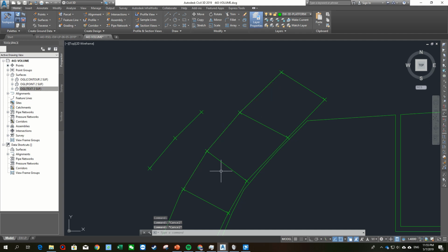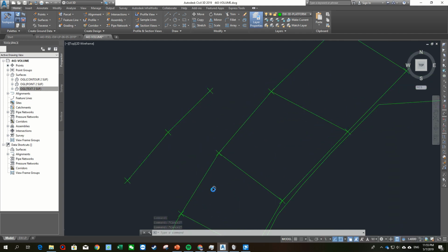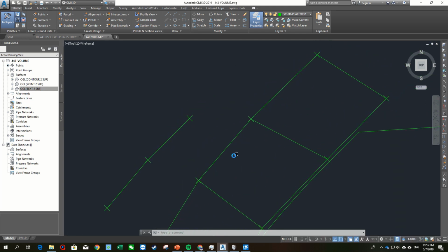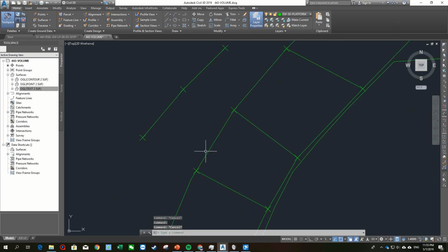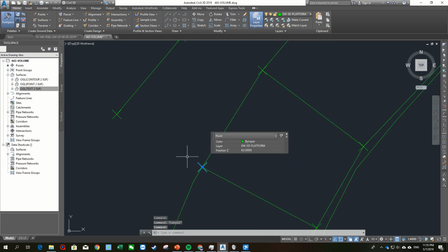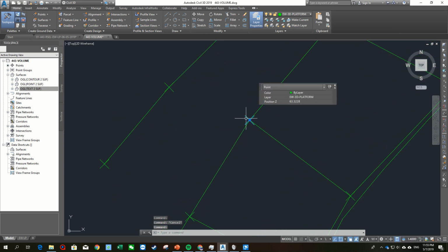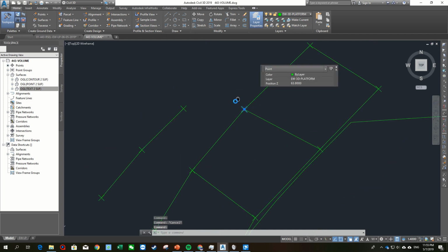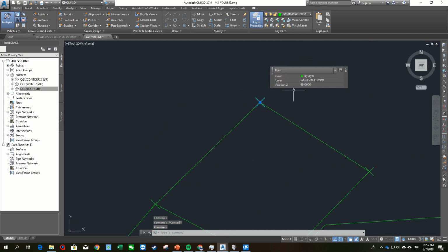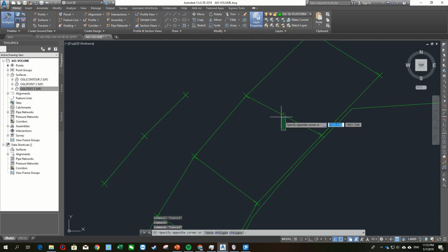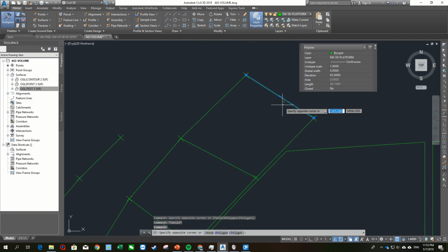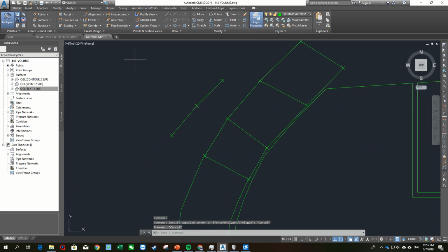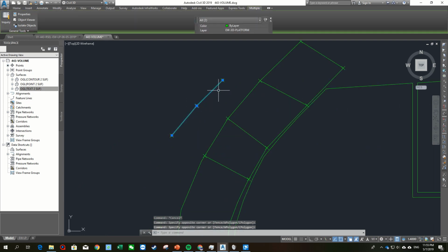So for this road, you need to create two contours which are 3D, but in 3D if you have different levels, which is from 63 up to 63.38. This is what I want the road to look like, 65. And this one in between that, you can use polyline to connect these 2 points, but if you don't want to also, never mind. This is an example. Okay, so we go back to here.